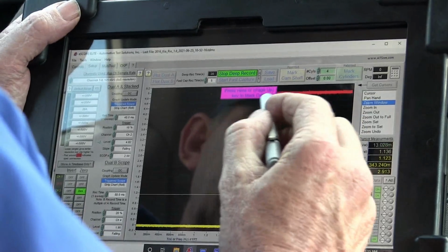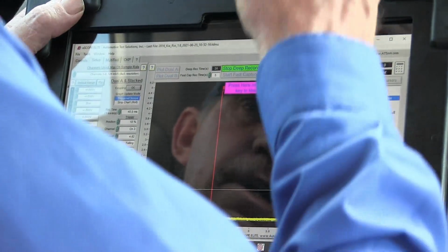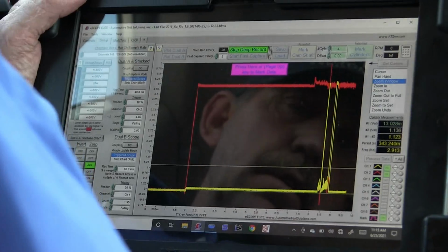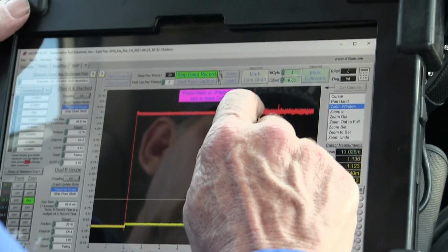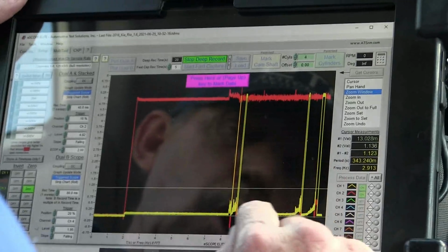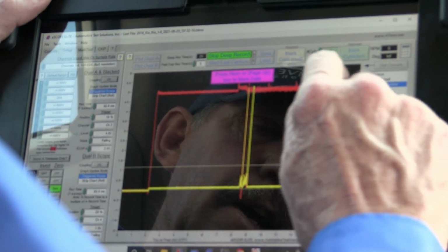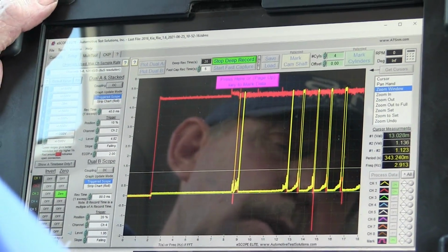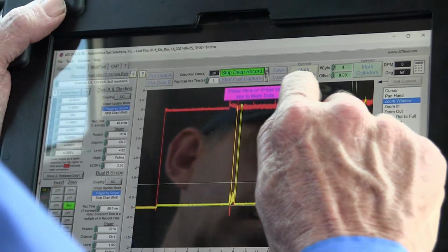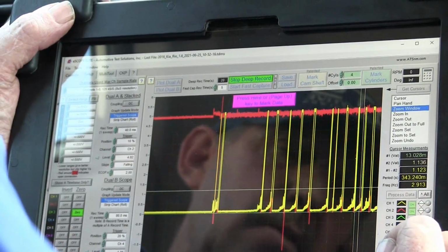So we can see we've got 5 volts. We've got our sensor pressure down here. Now that's interesting. Look at that, it went all the way to 5 volts. So that's an open circuit. That would show too much, not too little. We weren't having a code that said it was too much voltage. We had one that said we're low.